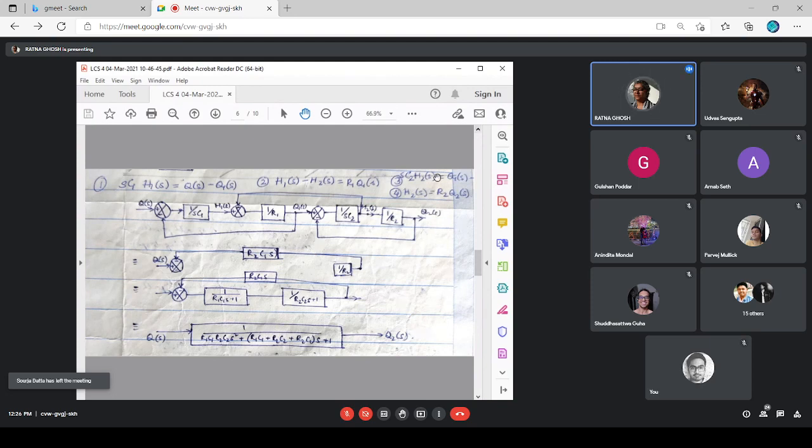But since this is a summer and this is a summer, and there are three entities here, moving it here just took up three of these. There was already the signal coming in, this also. Since you're moving it to before this, naturally this gets multiplied by the inverse of this one. Because you're shifting this one, the same logic applies.